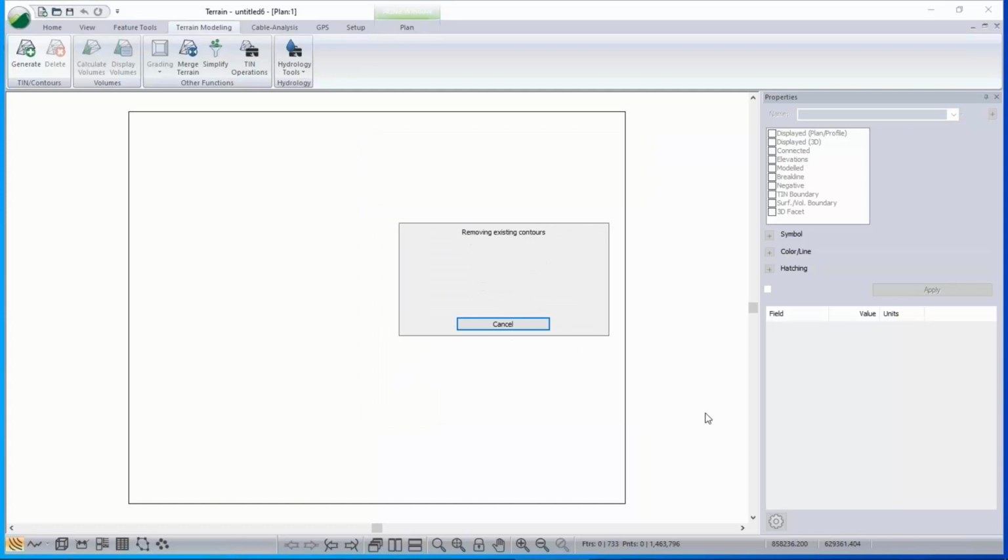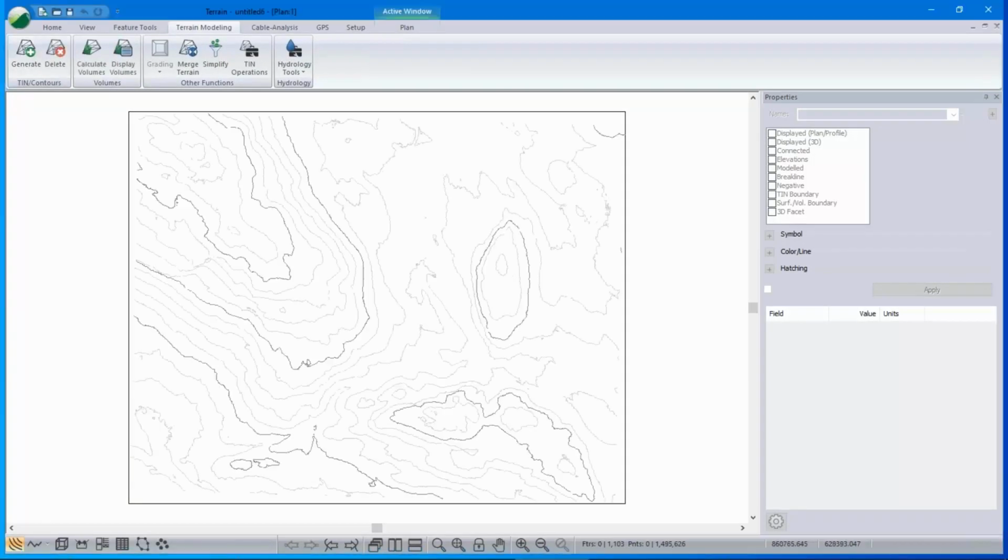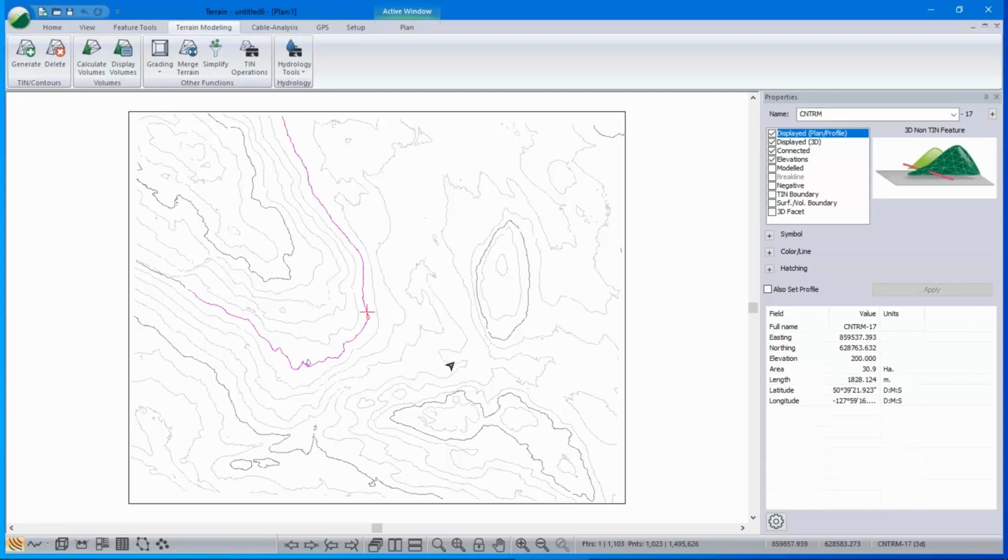So a large data set doesn't take that long, really. It's already finished creating the surface. Now it's generating the contours. An important point about contours: they really are just throwaway features in our software. The contour has an elevation defined, but it doesn't define the elevation. The elevation is defined by the underlying lidar points and the triangles.